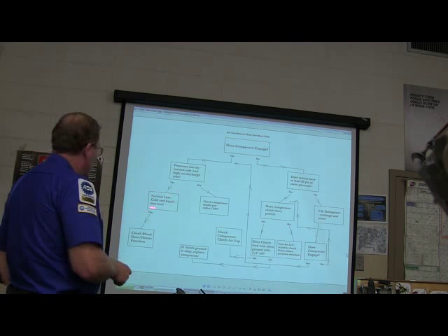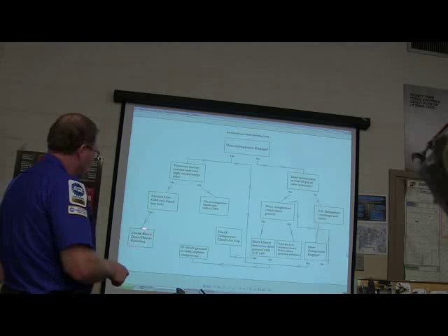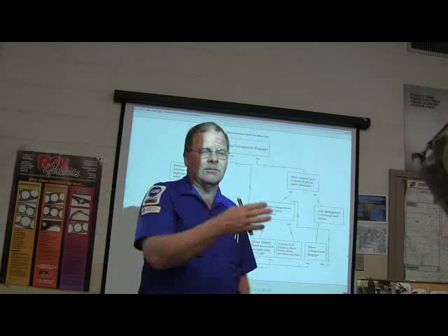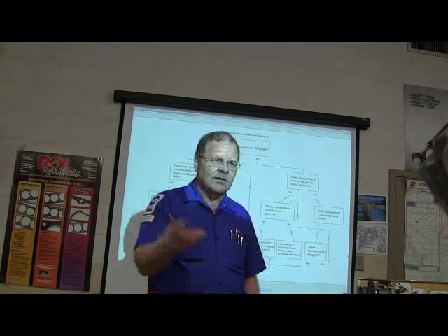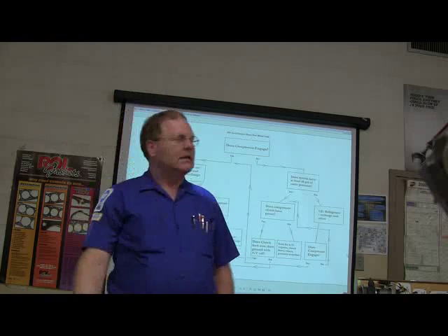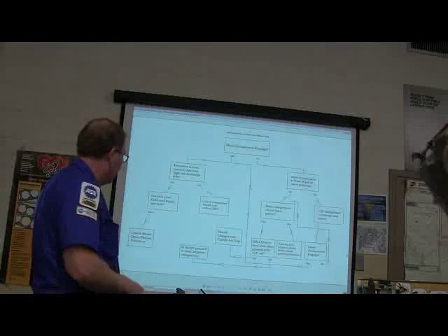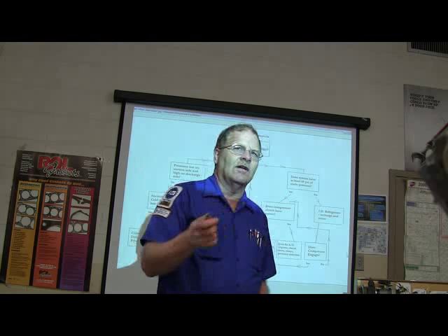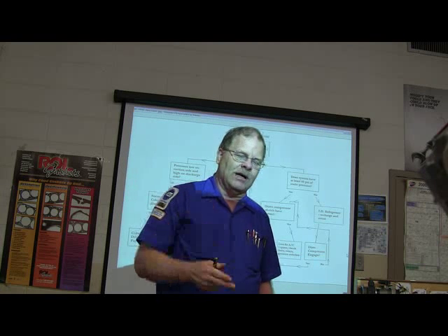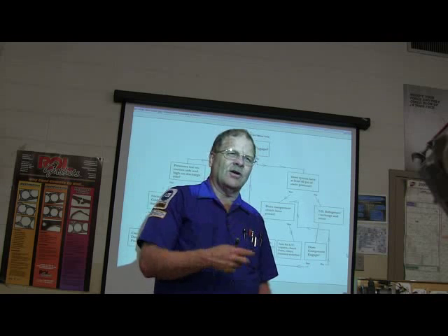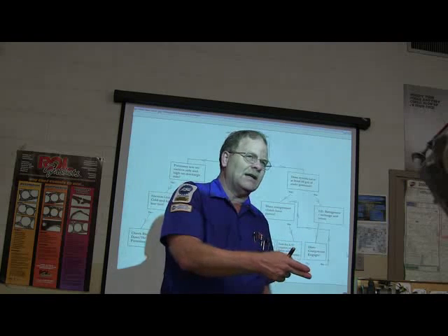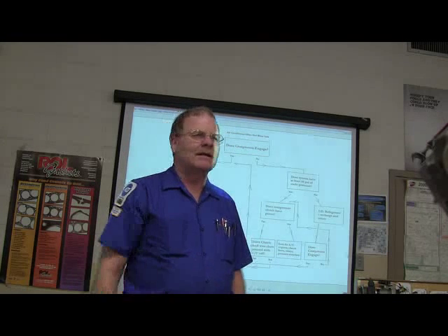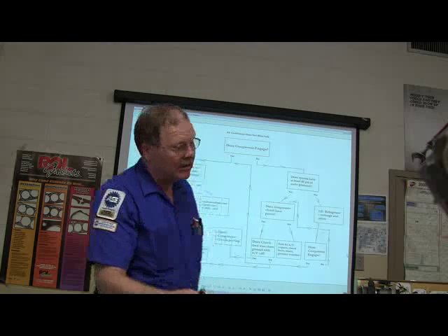If this is really cold and the liquid line is hot, you're going to check for a problem with your heater. If the blend door is moved to the point where it's got hot air mixing with the cold air, you're going to have warm air even though everything out under the hood is working right. So that's an important thing to look at. One of the ways you can do that, and I talk about it in these sheets, is make sure you know which way the coolant flows through the heater hoses, and then you pinch the one that's going into the heater core. Don't pinch the one coming out of the heater core. Why is that a bad idea? It'll bust the heater core. Yeah, and you don't want to bust the heater core because it's a pain to change that darn thing. Pinch the one going in.